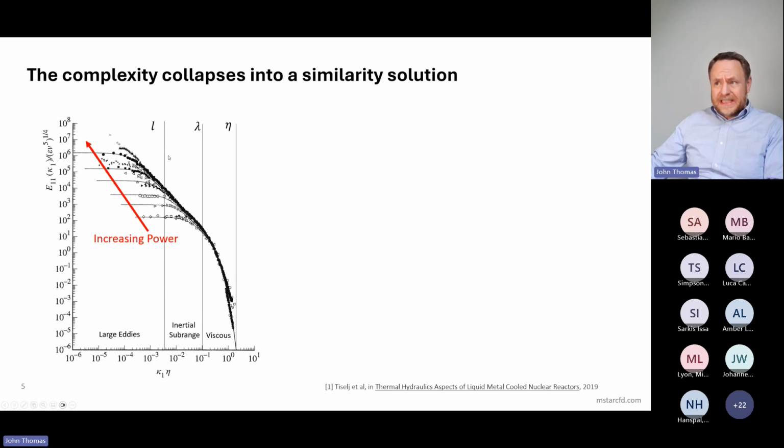Large eddies, again, with an integral length scale characteristic of the impeller size, nozzle diameter, vessel tank size, etc., are these big, overreaching eddies that inform bulk transport. They will be strongly correlated to system topology. They will be strongly correlated to impeller type. Because, of course, the topology of that oar, that flap, that nozzle, the tank shape is driving the type of eddies that exist. But as soon as you get down to this inertial subrange, and as you approach the Kolmogorov length scale, the integral scale is forgotten. All we're remembering, as it were, is the turbulence physics driving that cascade down to dissipation.